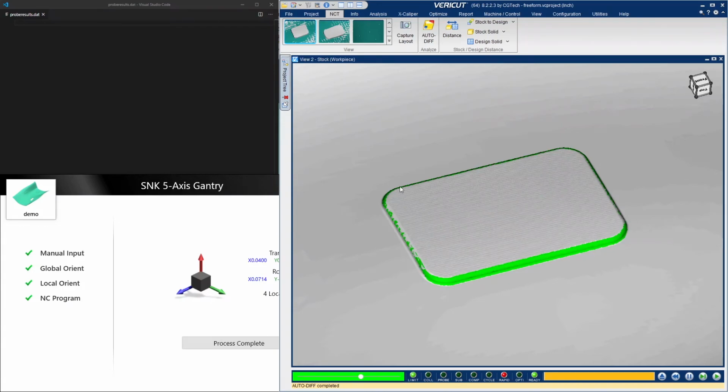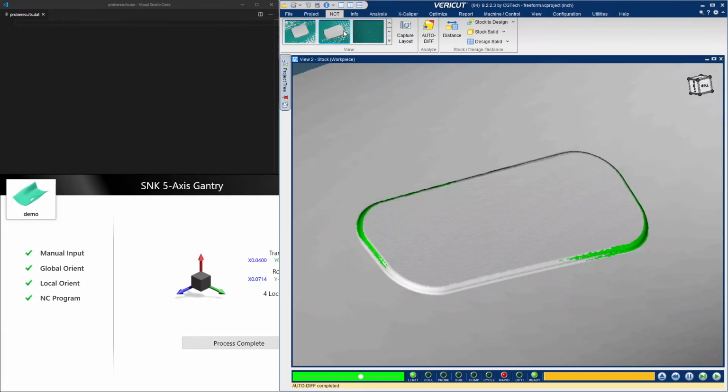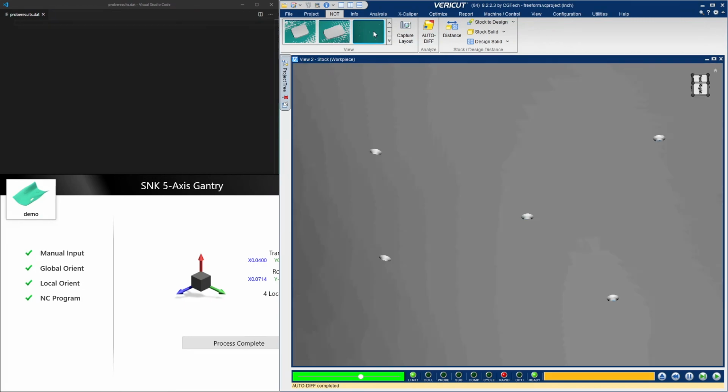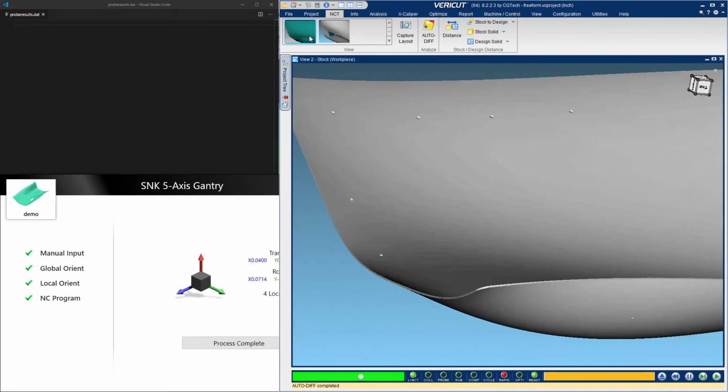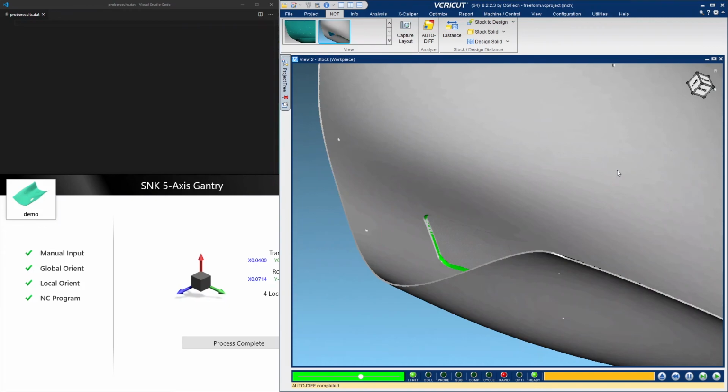The contour around the outside, the blending is off just a little bit, just a hair, because of the way that we set up our operation in NX. But we can see that the correct transformation was applied to it because the top surface of that pad is spot on. Then we can see our countersink depths are drilled to the correct depth. And we can see the periphery of the part, there is no excess and no gouging on any side of this part.